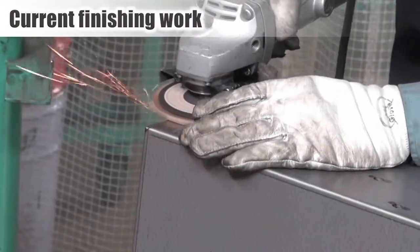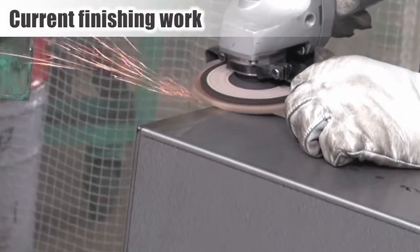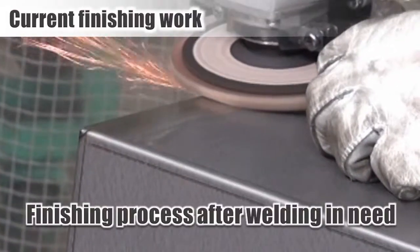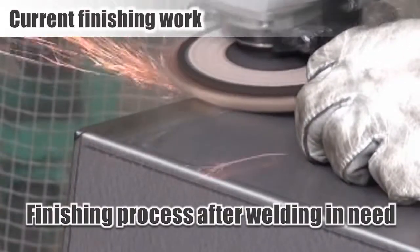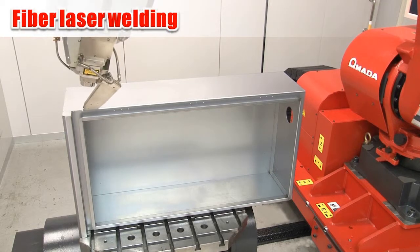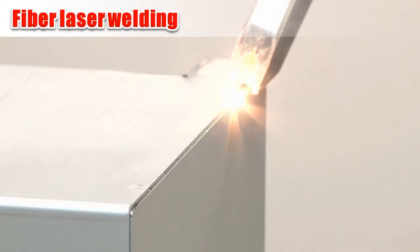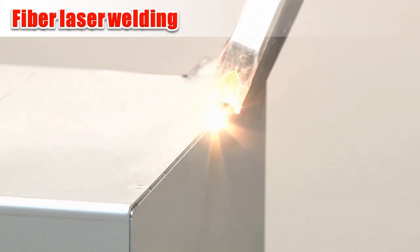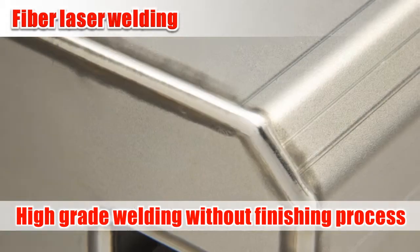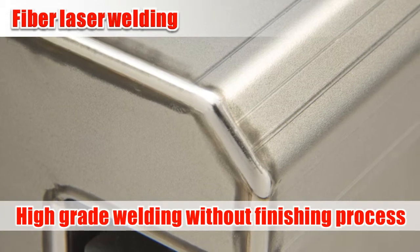Next, our proposal is for reducing the finishing process. With general welding such as TIG, finishing process is required after welding. However, the latest high-grade fiber laser welder doesn't require finishing process, and significant lead time reduction is also possible. Less heat distortion is one of the main characteristics of fiber laser welding too.